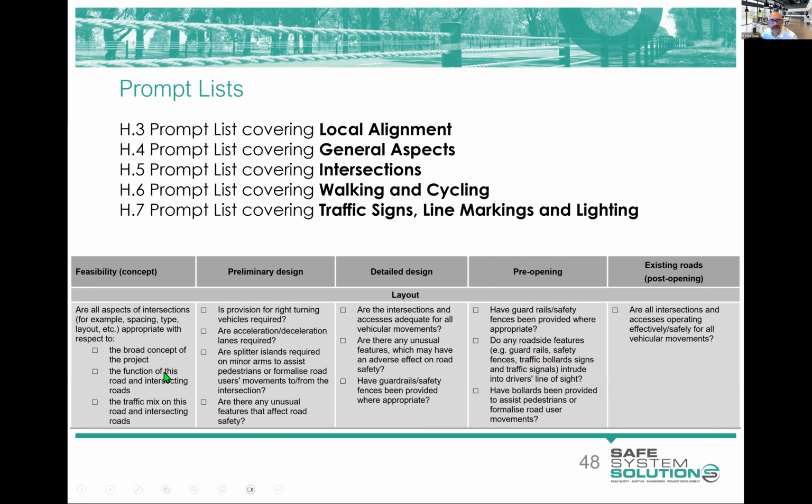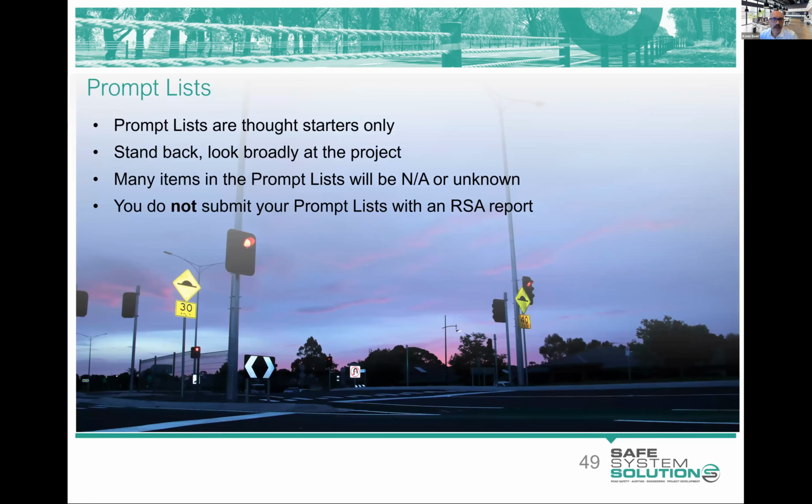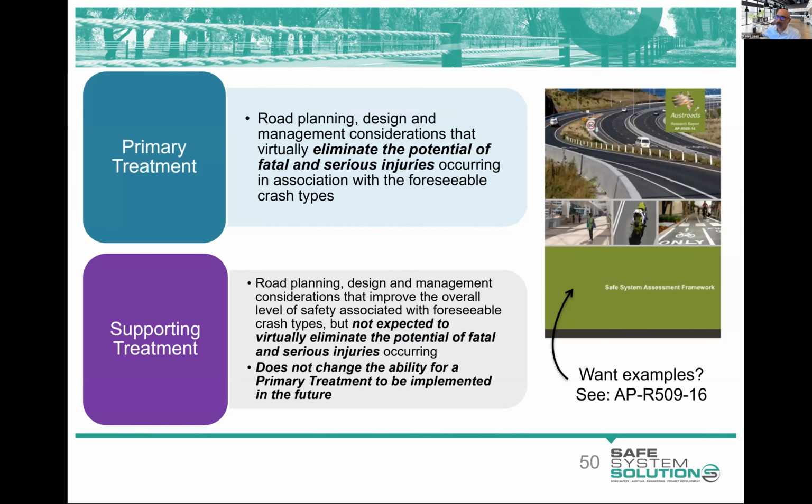You don't hand your checklist in, you don't put these questions into your audit, they just prompt your thinking. You might go, oh yeah, it's a good point. I hadn't thought of that. Right. Oh, we better consider that in our audit. So they are thought starters only. What you have to do is stand back, look broadly at the project, at the scheme, and use those to prompt thinking. There's going to be heaps of them in there that you will put as not applicable because they're trying to cover all road scenarios. And you don't submit that prompt list as part of your road safety audit report. So that's all I really wanted to say on prompt lists.